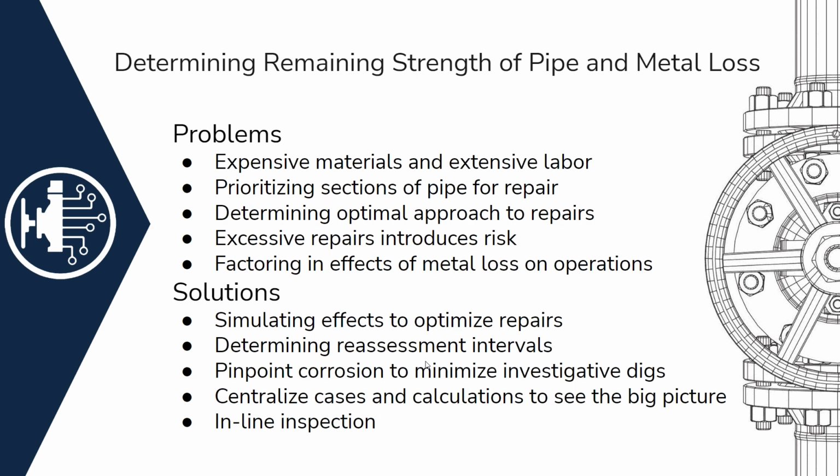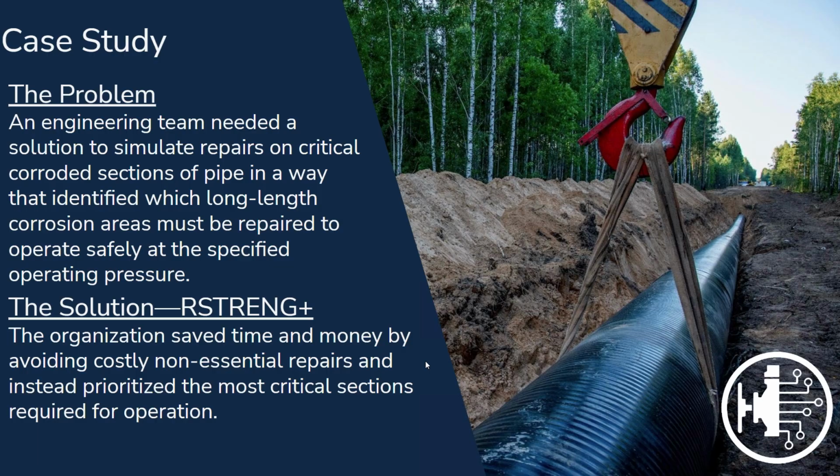So what are we talking about? Now that we saw that, it's bad enough. We've got the cost of pipe materials. Now we need to think about the repair materials, the labor to put them on, and something like that would have to be a cutout. I'm not saying you couldn't put a sleeve on that, but I wouldn't want to even attempt it because of all the issues with that particular piece of pipe. That would be a definite cutout in my opinion.